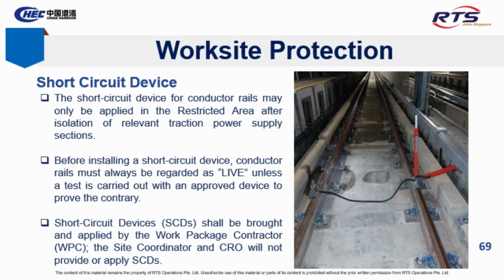Slide 69. Short circuit device. Short circuit devices, SCDs, can only be used after traction power is isolated. Always treat conductor rails as live unless tested safe. SCDs are issued and installed by WPC.